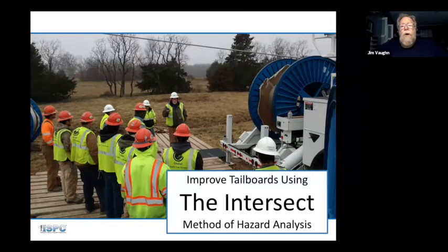What they didn't know was that in the previous 10 years, when the plant went to auto control systems and supervisory control systems, they had put a power supply in the loads on the line side of the switch, to keep the controls powered up so they could open and close these breakers remotely. But nobody ever changed that.